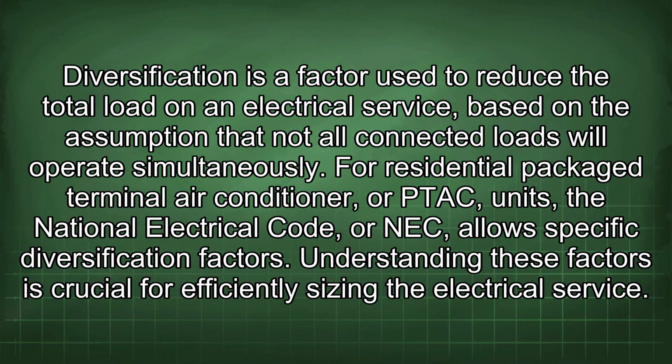Diversification is a factor used to reduce the total load on an electrical service based on the assumption that not all connected loads will operate simultaneously. For residential package terminal air conditioner, or PTAC, units, the National Electrical Code, or NEC, allows specific diversification factors. Understanding these factors is crucial for efficiently sizing the electrical service.